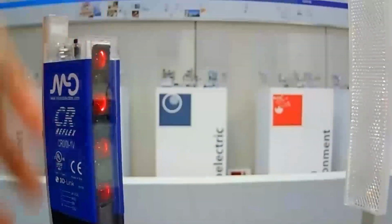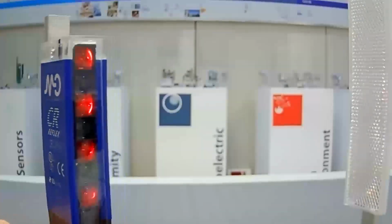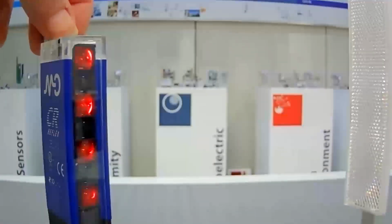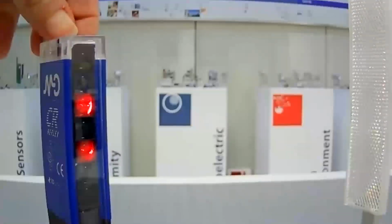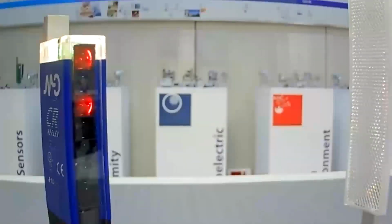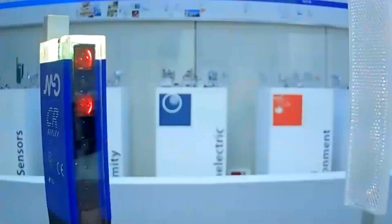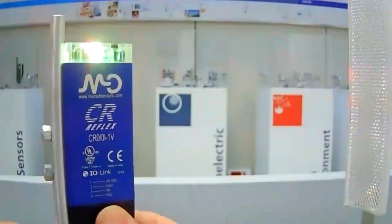And now, as you see, the LEDs are blinking. This means that you are entering a setup menu. So by just pressing the teaching button, you can simply deactivate a beam. In this case, we are operating with only 2 beams. So if you have a fixed part of your machine in the bottom part of the sensor, it's possible to install this sensor like a standard sensor.